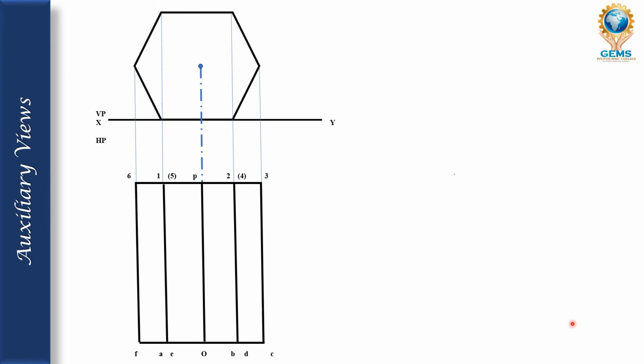Now, if it is inclined at 45 degrees from the vertical plane, how would it look? For that I have to first draw the 45 degree line. This face is 25 and this height is 60 mm. So the base is 25 mm and the height is 60 mm.